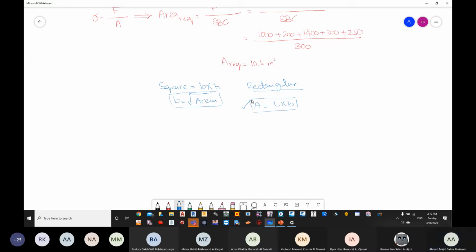Okay. So, as we used to have in the last classes, we have another dimension, which is the width, for example. They have given us that the lateral dimension has been restricted to this much. And I have told you, if it's not given, you need to go and use the ratio of the column. But the problem here is that both columns are square, and my combined foundation cannot be square, or it's not logical to be square.